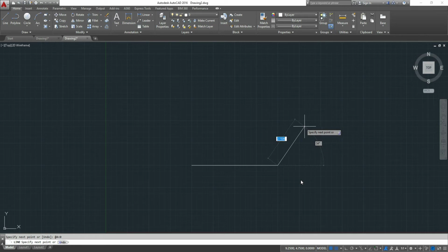and it draws a line 4 units long at an angle 0. If, for example, I wanted to draw a line 4 inches up using the Cartesian coordinates, I could hold down the shift, press the @, so for my X I'll enter 0, comma, and for my Y 4, comma, and it's the same thing as @4 at an angle 90, but I just use the relative Cartesian coordinates.